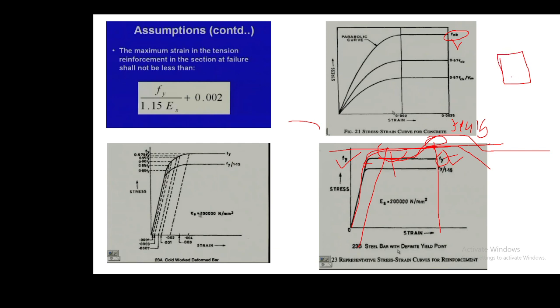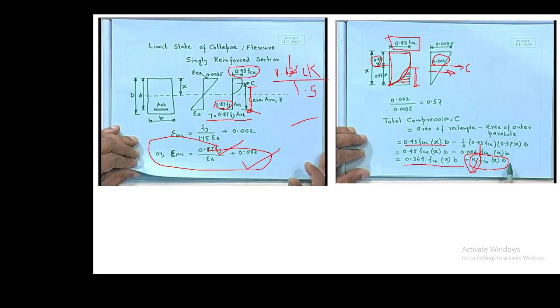Both should have similar strain. If one has higher strain than the other, then stresses develop, and whichever is weaker will fail. So that's why the Fy of the steel is considered for the design and not the ultimate.